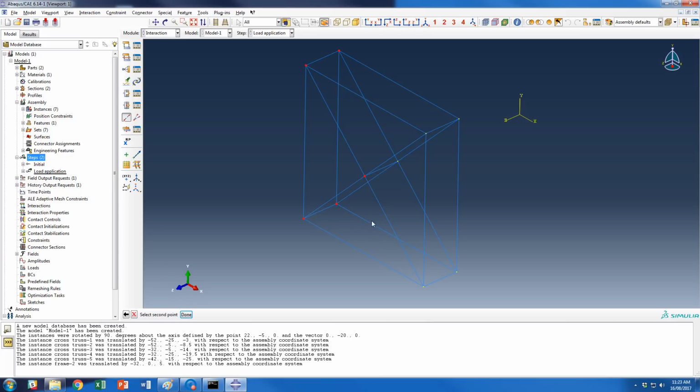So you may select the frame as the first point, and then you will be selecting the cross member as the second point if you click. Just make sure that when you click, here it's saying select first point, and if you misclick outside of it, it'll still say select second point because you haven't selected the second point. So you just want to make sure you get directly over it and then click again.